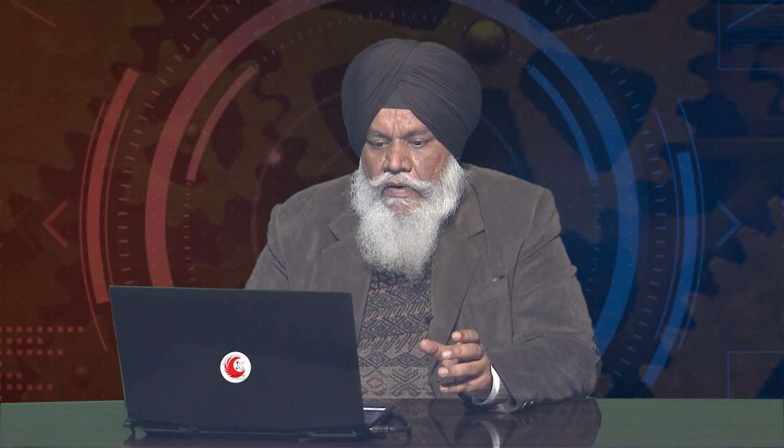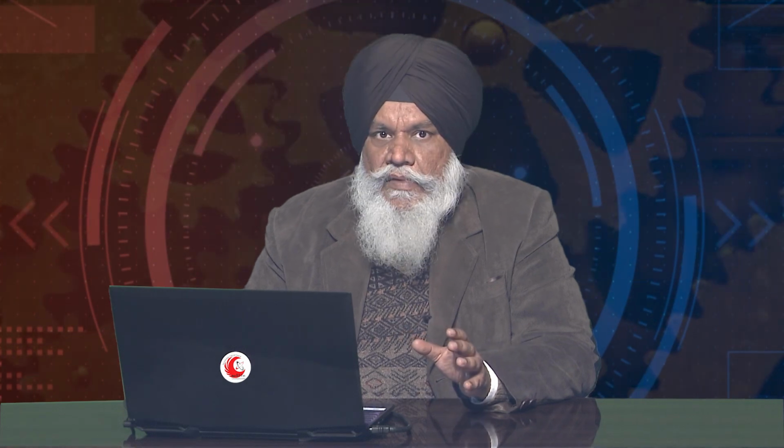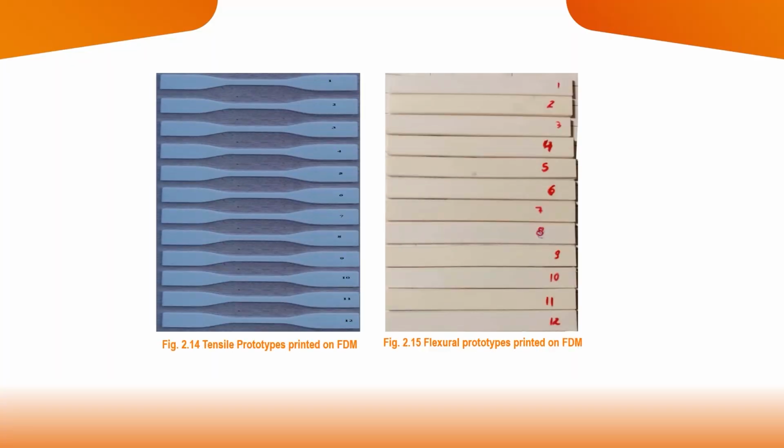Similarly, all 12 sets of experiments were performed with different combinations of ABS and PLA. Again, I want to remind that this is a selection based upon random numbers. No specific pattern was selected. These were the specimens that were actually prepared with these combinations. This is the dog bone specimen as per the 12 sets of readings that we have selected in this table, and similarly the flexural specimens accordingly.